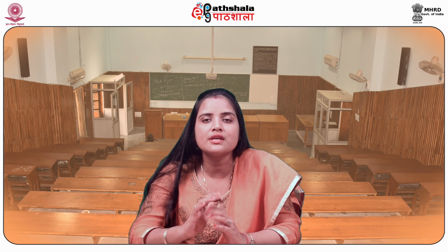Now, beginning with what is electron beam lithography? Electron beam lithography or E-beam lithography is a technique which is used to draw patterns over a substrate by using a focused electron beam. The surface of the substrate is covered with an electron-sensitive film, which is also termed as resist. It does not deposit material onto the surface, rather it changes the solubility of the resist which is already present on the surface.